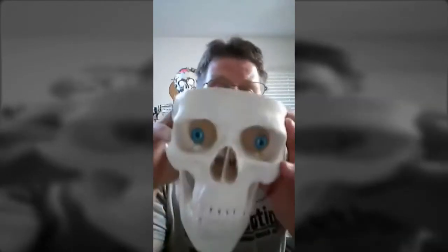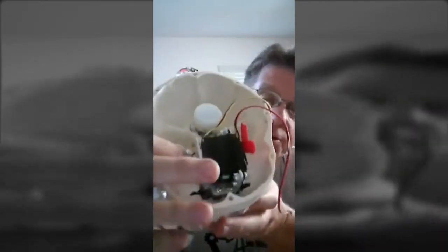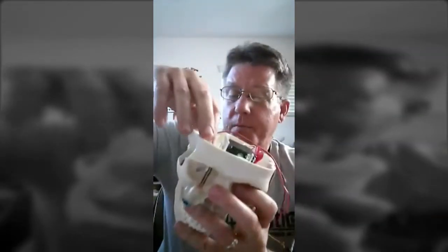And when we're doing even the OLED eyes or the TFT eyes, we have to do some different things because we need to be able to set those screens back in the back of the eye sockets, and it takes a ton of grinding and removal of material to be able to get those screens back in here. So if you want moving eyes, that's a considerably increased level of difficulty.